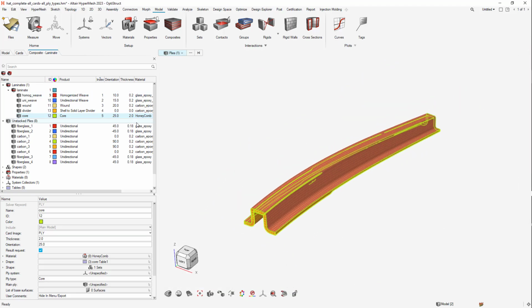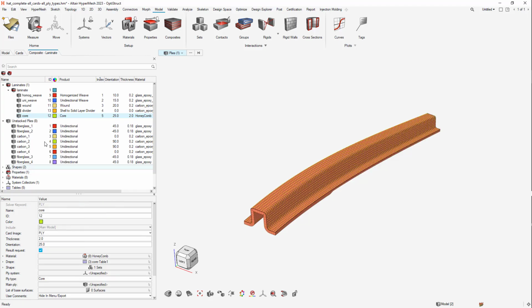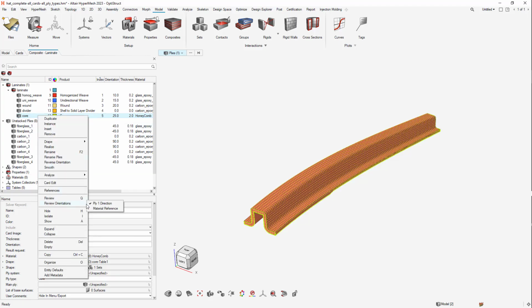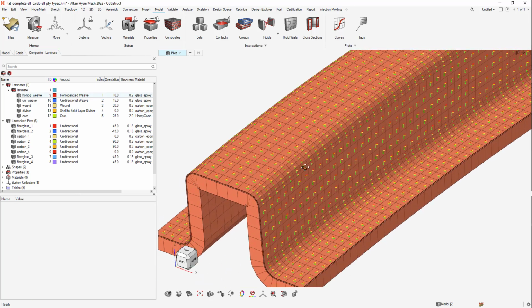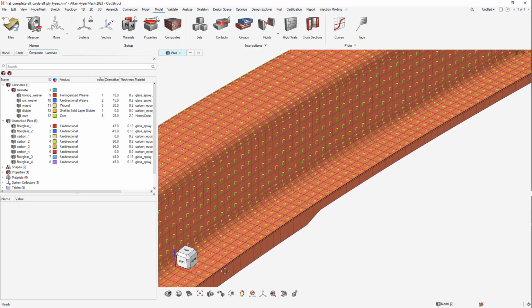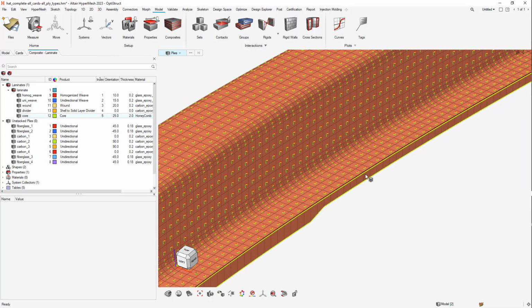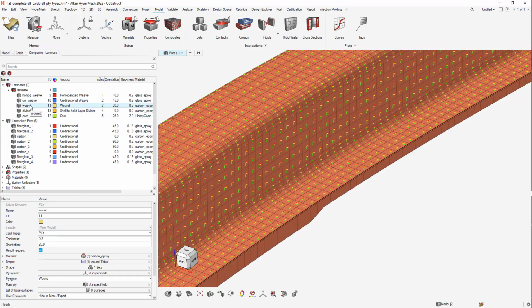To illustrate that a little bit more, we can review all the plies separately. And for that, let's enable the orientation review here. So we can first see, okay, our core material has the 25 degrees, but the main focus here is actually on the thickness and basically the ramping between the different thicknesses on the model. Then we have our divider slide here. It doesn't have a thickness, doesn't show in the list as we've seen, so nothing really important to review.